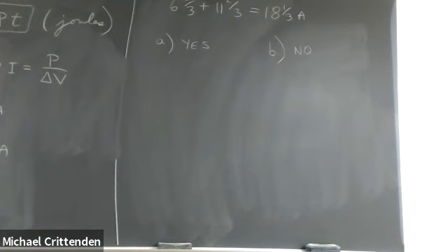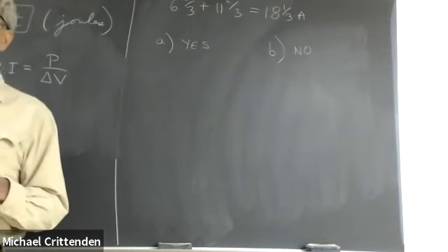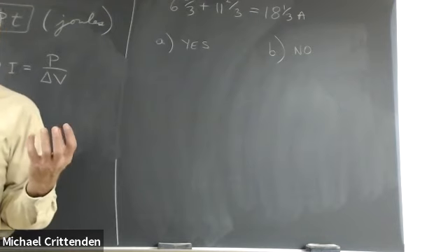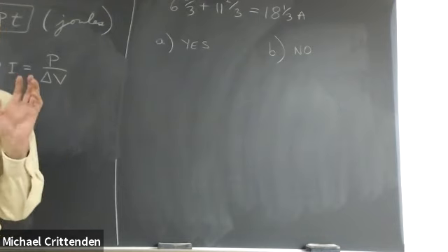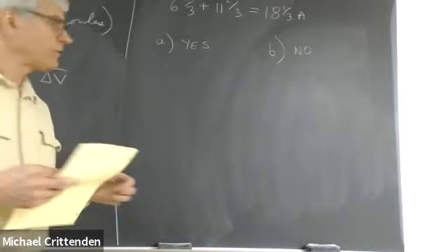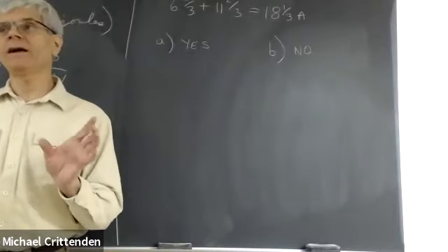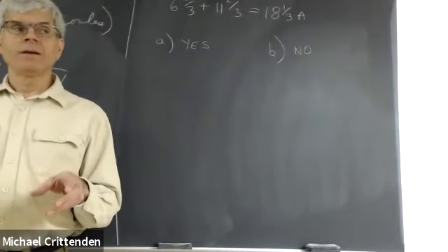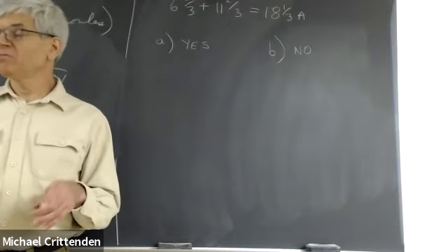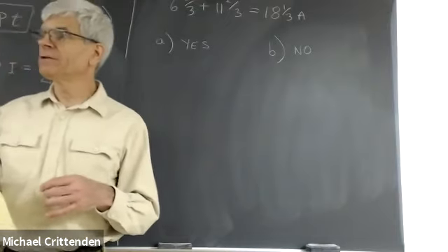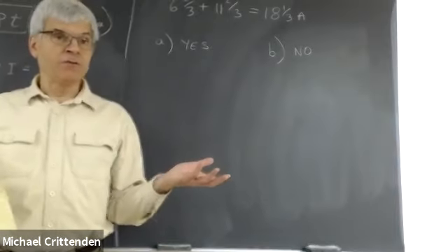Well, let's see, we've got about 7 or 8 minutes left, which is just enough time to get through some introductory stuff about Kirchhoff's laws. First of all, terminology. EMF. You already encountered this one the other day when you did that lab with the dead battery. Basically it's the voltage of the battery. If you've got a 1.5 volt flashlight battery, assuming one that's in good working order and not 15 years old, the EMF is 1.5 volts.